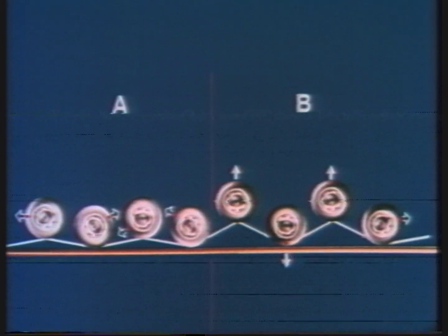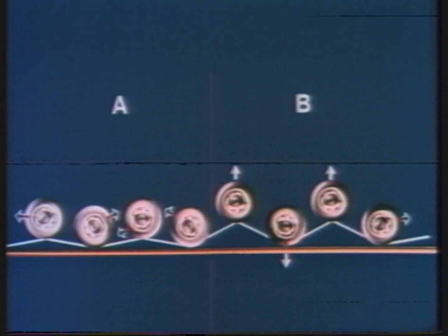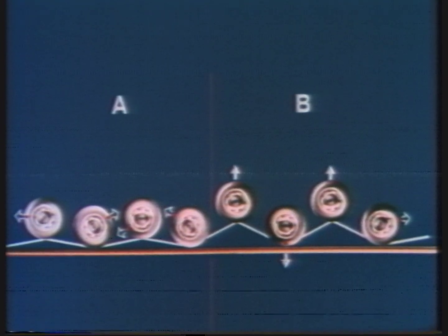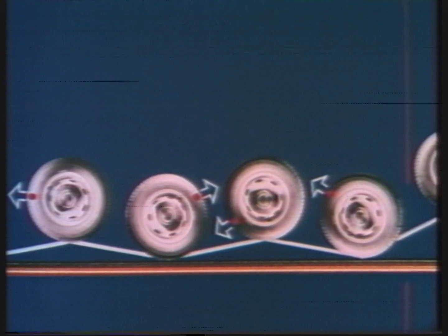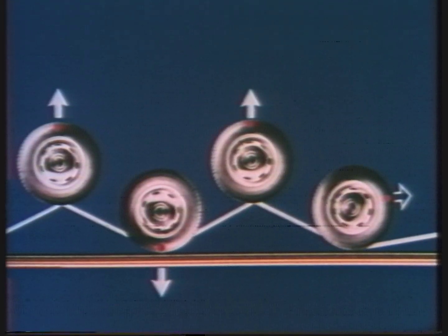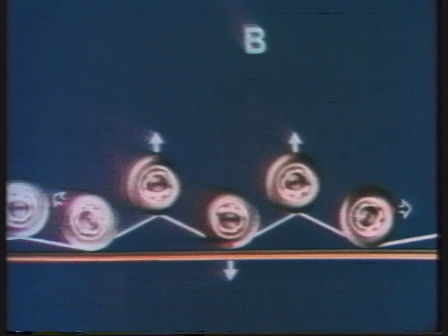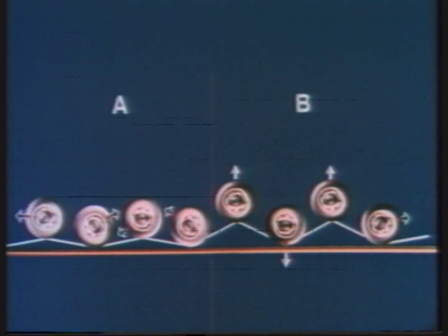The wheel, with its inflated tire, also has a vibration frequency of its own. In other words, it has a tendency to bounce, rather like a tennis ball, at stage A. So when the out-of-balance forces we've talked about match the wheel's natural frequency, they are magnified, shown at stage B. This is why out-of-balance vibrations increase and decrease in both the lower and upper speed ranges.